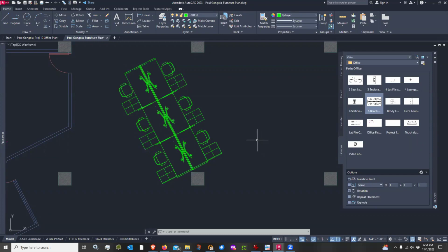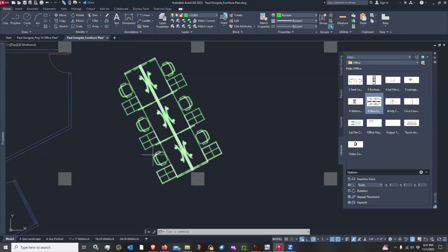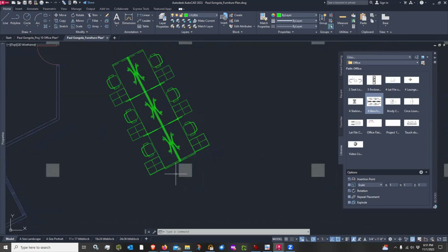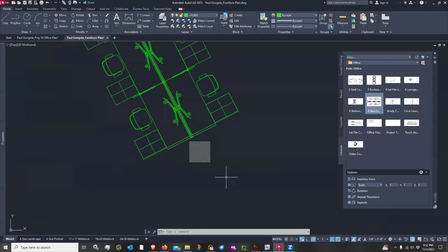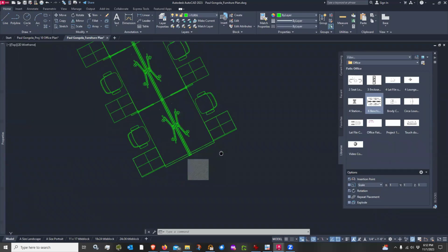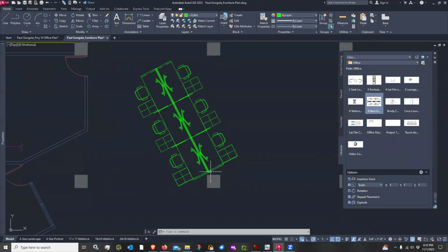So what we need to do, though, is bring power to the workstation. When you're locating workstations, generally speaking, you want to try to locate them near walls or columns or something like that, where you can have power coming in from the building and then whip into the workstations. This workstation grouping here is near this column.